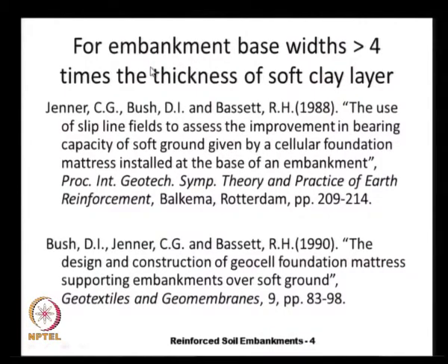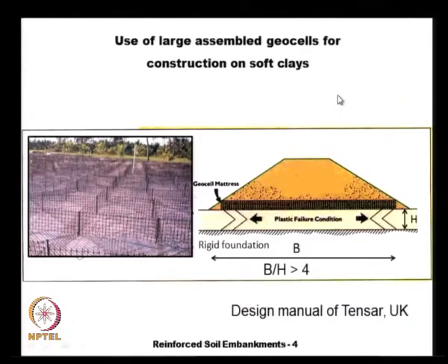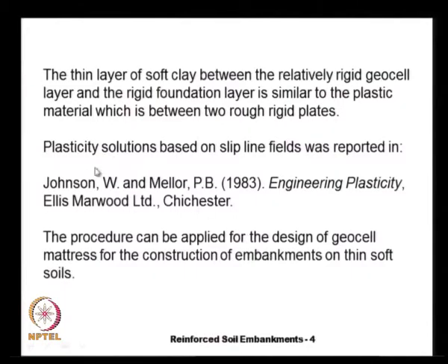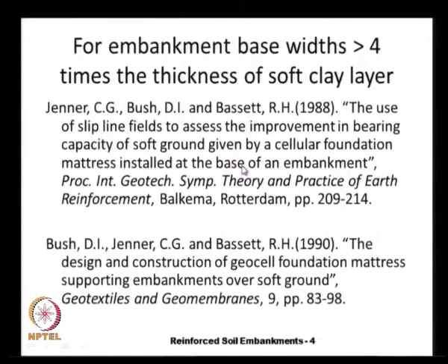And this particular procedure that we are going to discuss is only applicable for the case where the embankment base width is greater than 4 times the thickness of the soft clay layer. Actually, this is our embankment base width B like this, and the height h of the thin soft clay layer, and B by h should be at least more than 4 for us to apply the theory derived by Johnson and Mellor based on the slip line fields.